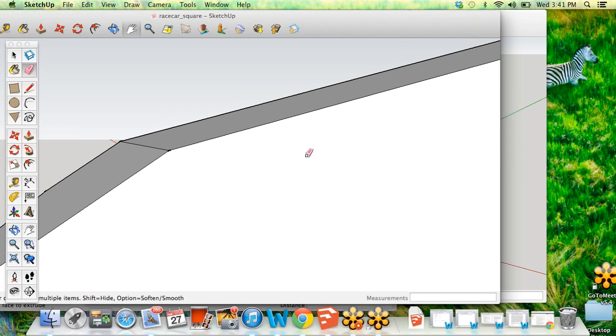So if you guys remember, to create an arctangent, you use your arc tool. You select a spot on the edge where you want to start the arc, and a spot where you want to finish it, and then you can see when you press the start and stop, there'll be the option where it's purple. You can choose that one, and your tangent is going to be really smooth, and when it pops up again, the curve will be purple.